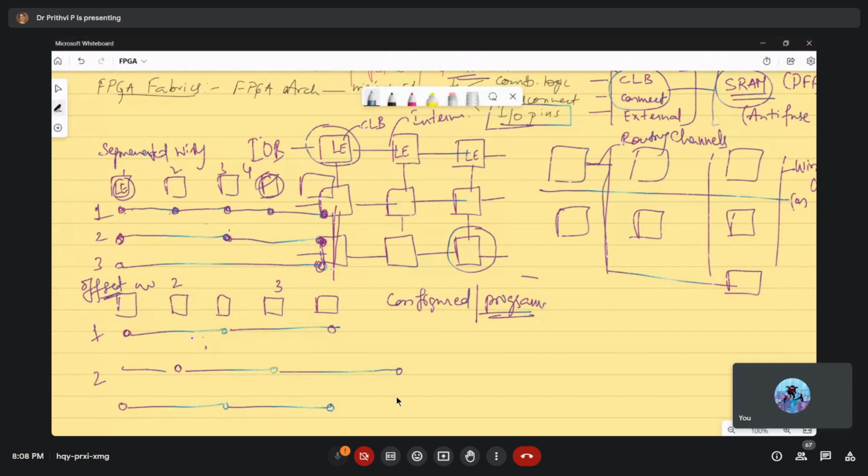designing or developing an FPGA, what his goal or aim has to be is, in a given space, say this is my FPGA space, how much logic I can fit, or how many blocks I can fit into that, has to be first identified. And how many input output pins have to be given for a given area and given number of logic blocks inside. Say all different logic blocks in a given space, how many such blocks I can incorporate, and how to address all these segments, how many inputs I have to give or how many outputs I have to take has to be decided.